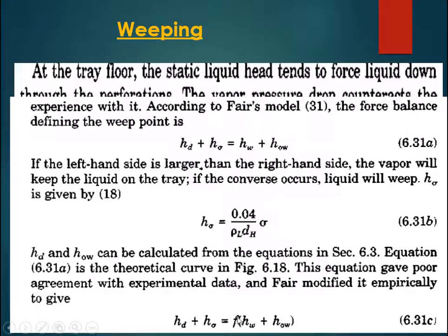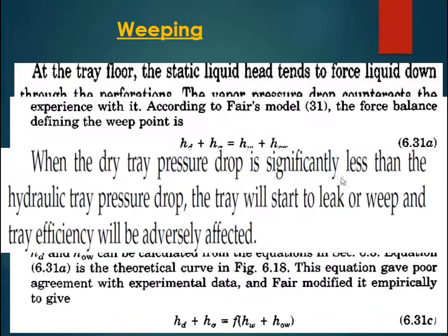And here F is the aeration factor. So according to Henry Kister, it is the dry tray pressure drop which balances the liquid head.